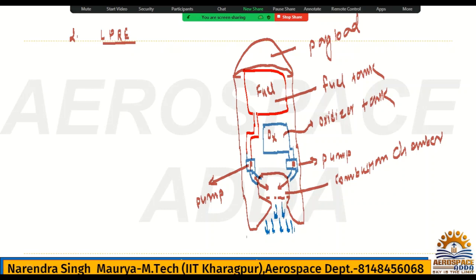So basically this is the nozzle. So two tanks are required. One is the fuel tank, another is the oxidizer tank, and both are in liquid form. The liquid will be taken from the tank to the combustion chamber with the help of a pump. Suction pumps will be there. So see, two tanks required, two suction pumps required, sometimes a regulator also required, or a gas generator required. So it is very bulky, very spacey, taking more space compared to the solid propellant rocket.